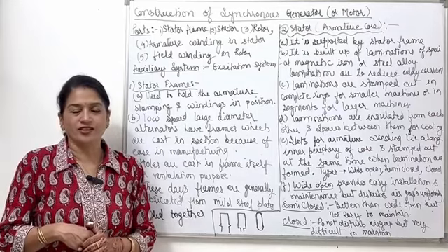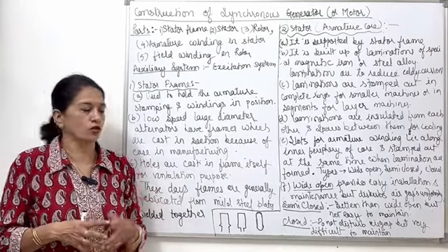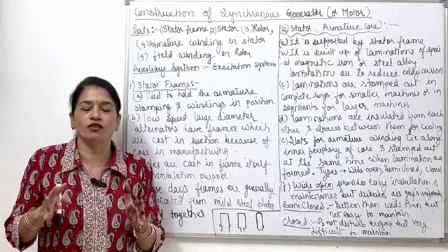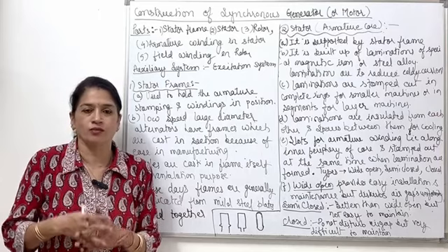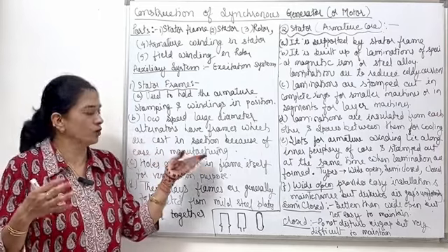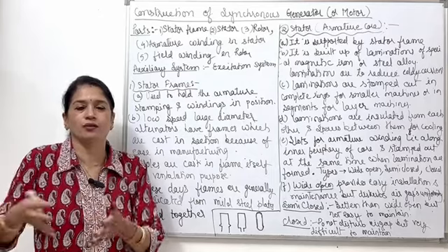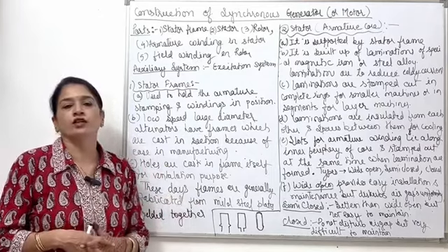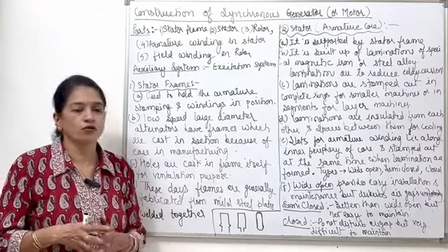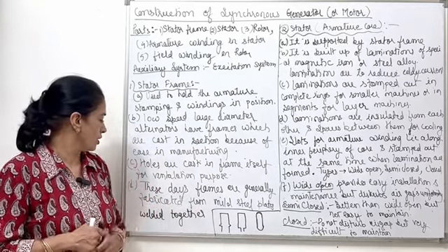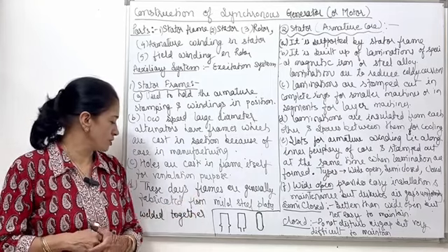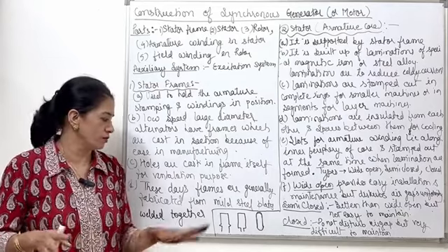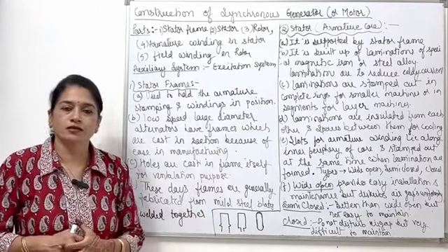Alternators with low speed and large diameter have a large structure. In those, the frames are manufactured or cast in sections for the sake of easiness, and later, at the place where we have to install the alternator, they are welded together. Also, holes are provided in these frames for ventilation. Nowadays frames are generally fabricated from mild steel plates which are welded together. Now let's discuss the stator.